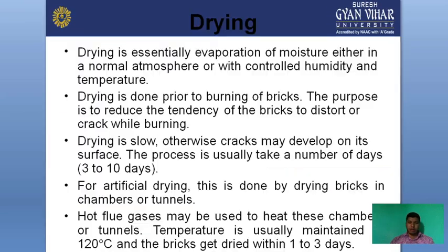Drying is essentially evaporation of moisture either in a normal atmosphere or with controlled humidity and temperature. The second point is drying is done prior to burning of brick. The purpose is to reduce the tendency of brick to distort or crack while burning. Drying is slow, otherwise cracks may develop on its surface. The process usually takes 3 to 10 days. For artificial drying, it is done by drying bricks in a chamber or tunnel. Hot flue gases may be used to heat these chambers or tunnels.